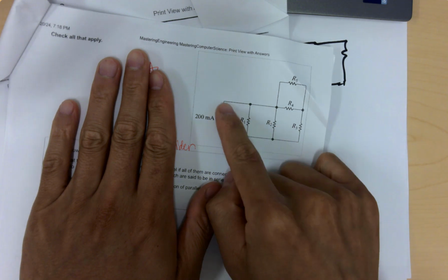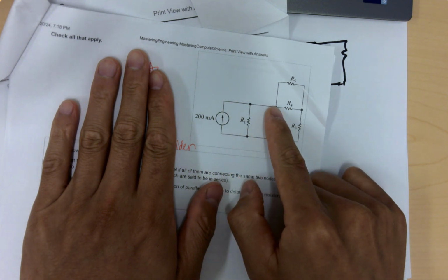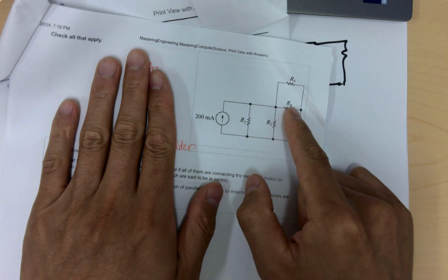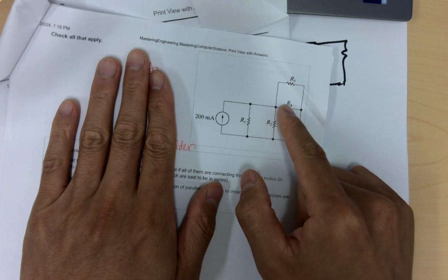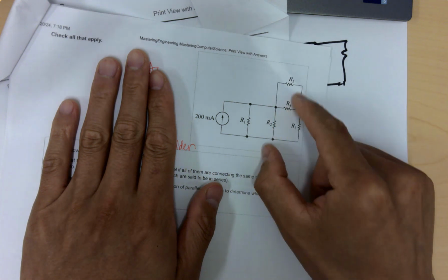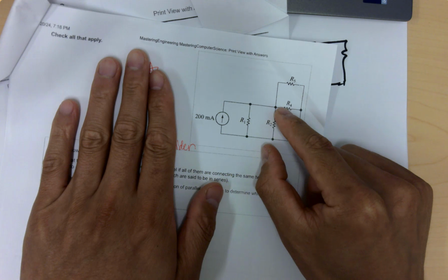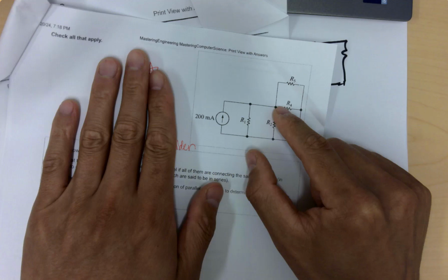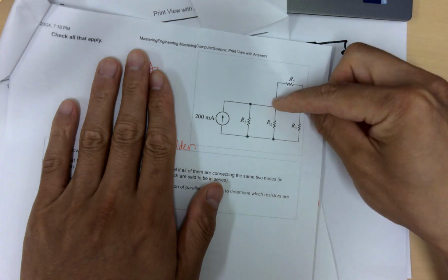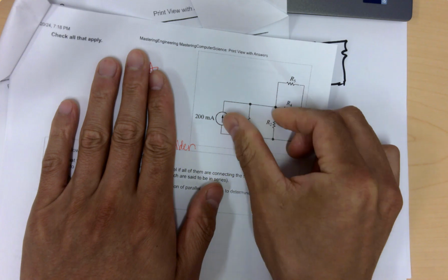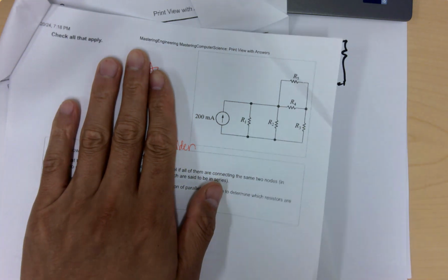Current flows through here to this point, and it's divided or split into two branches over here and merged over here. So first we can combine these two parallel resistors into one. R4, R5 could be just one resistor, and you can draw it here. Then that combined resistor will be in series with this one. Then you can do the parallel, things like that.